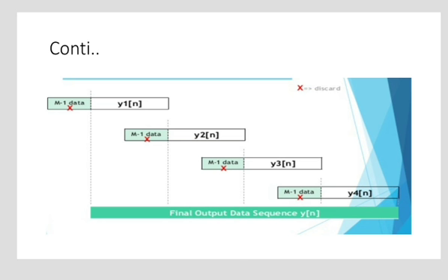Overlap save algorithm can be extended to include other common operations of the system. Additional IFFT channels can be processed more cheaply than the first by reusing the forward FFT. Sampling rates can be changed by using different sized forward and inverse FFTs. Frequency translation can be accomplished by rearranging frequency bins.